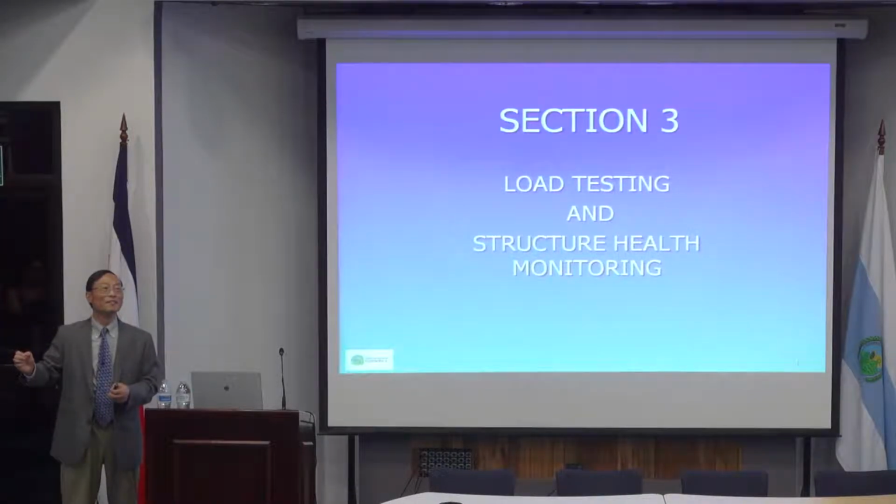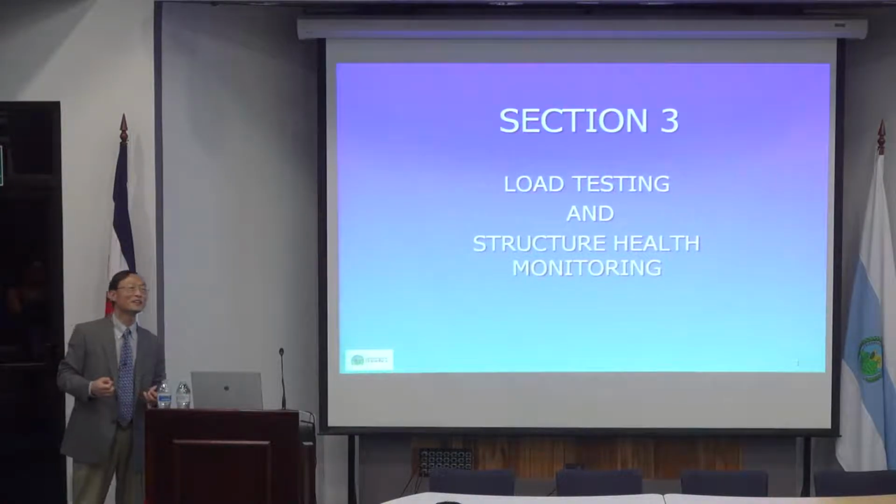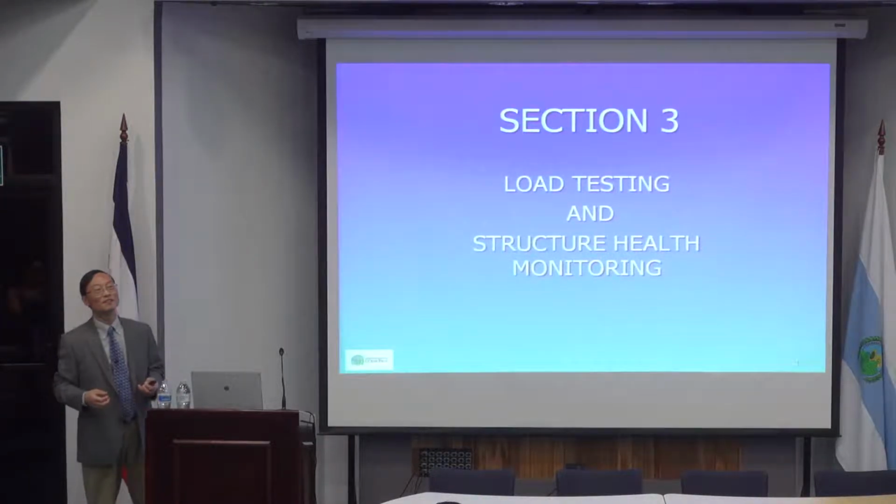Second thing, there's an impact, as I said. The impact of live load is almost 30%. And you know that most likely the impact is not that; typically it's like 10 to 15%, it's less than half.